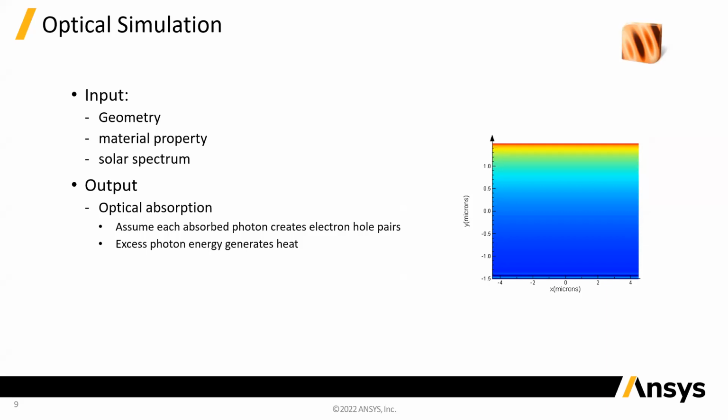Then when you run your simulation, the second part of FDTD is the time domain part. So that means that you run it in time domain. At the first time step of your simulation, you figure out, okay, light is entering my device, and you solve Maxwell's equations to see how the electric and magnetic fields are going to behave at the very beginning of your simulation.